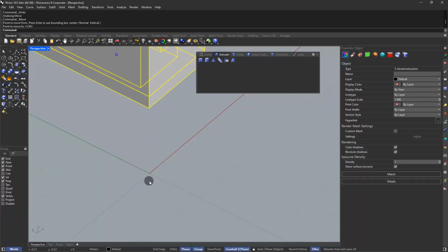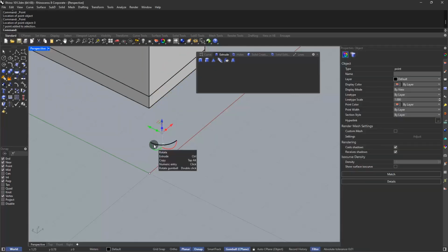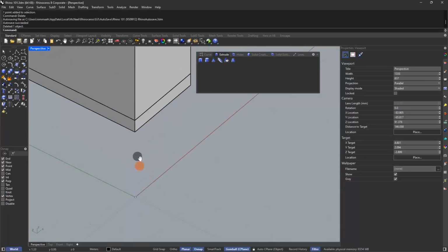We can create a point in 0, 0, 0 coordinates. So I will choose this single point. If you right click, you can create multiple points. For example, I right clicked here and I can create multiple points. But if you left click here, you can create just one point. And for next points, you have to use space or right click to repeat the command. I will type 0 and press enter. I will delete this point. I just use delete.